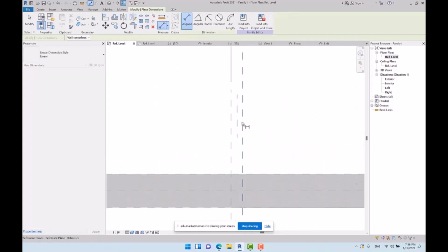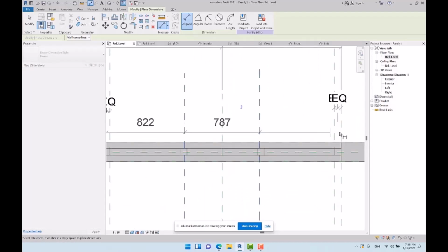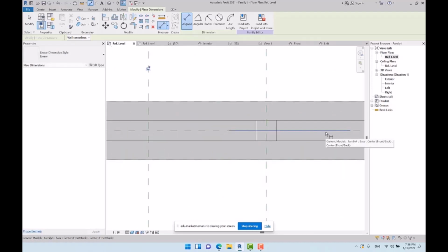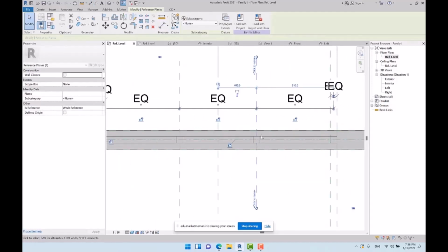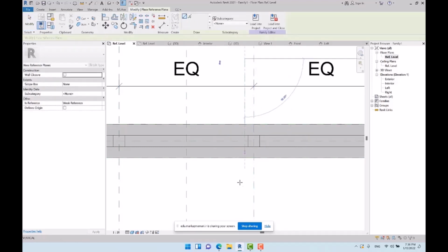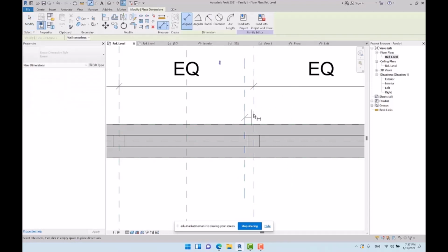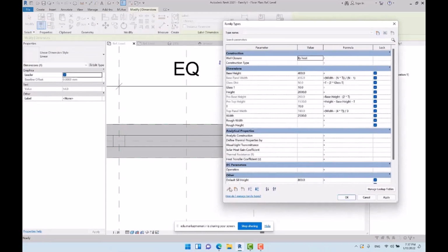I measure the dimensions and then equalize them this way. Then I'm gonna place the total dimension in relation to the new reference planes. We got 3 parts, equalized. Well done. So I have sketched 2 reference planes, and then I have added the total dimension equalized for the 3 parts. And actually I'm gonna specify the place of the profile as the position of the bolt of the door. I sketch a reference plane here, and then I measure the line distance to associate it to a new parameter. However, there is no necessity to measure this distance.